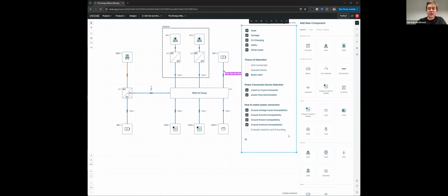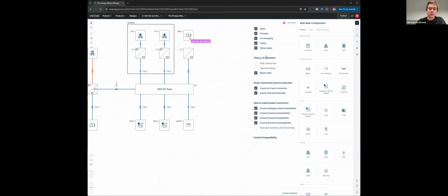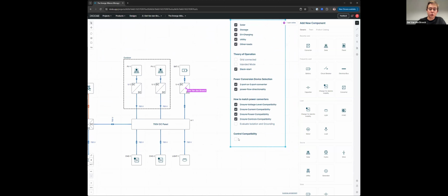And actually the same could happen if I replace that battery by a converter which ties a certain asset to the grid. Let's say I'm going to use this converter with a battery as a backup source to keep my DC voltage up. If these two converters would operate in constant voltage mode, so the central one and this battery one, they will start fighting each other.